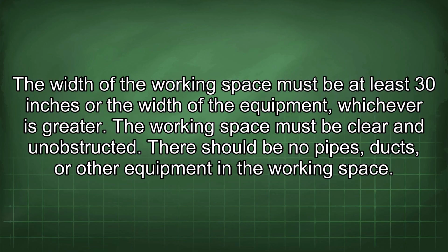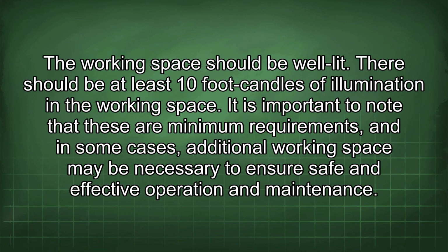There should be no pipes, ducts, or other equipment in the working space. The working space should be well lit. There should be at least 10-foot candles of illumination in the working space.